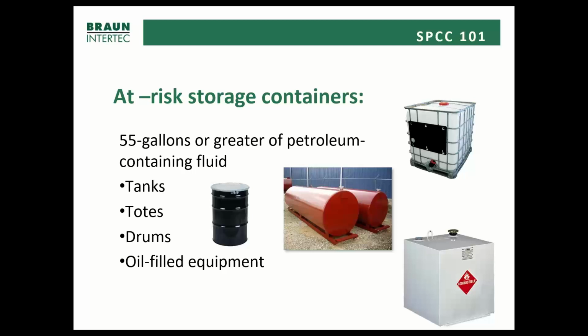And then we see if we've reached that 1,320 gallon, or the higher threshold of 10,000 gallons, of storage on your site. We're looking at tanks. We're looking at portable totes. We're looking at your drums. And then we're also looking at oil-filled equipment, whether it's something on a processing line that has a hydraulic fluid reservoir that's 55 gallons or greater, or elevators.